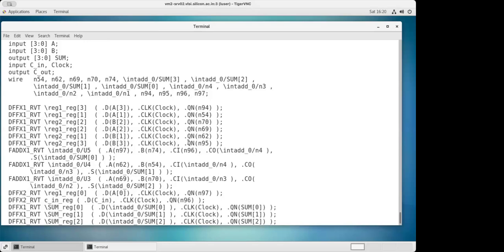So what the tool did, it picked that full adder directly with compile ultra. Initially in the normal compile, it was not picking any full adder, but when we did this compile ultra, it picked the full adder directly from the library, because in the library there is a full adder. So that's the reason it is capturing it as a full adder here. Okay, so this file is basically coming here. Is it clear, everyone? This is the same file, same RTL, but now it is represented as part of your gate level netlist. Make sense, guys?